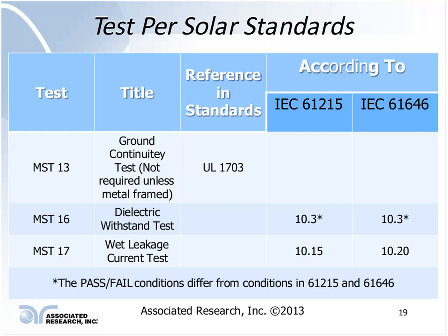There's actually a very similar table in 61730 that outlines the same information. I've basically broken that down and focused on the tests that I want to talk about here. And of course, this is in the interest of time. There are many more tests. Unfortunately, we can't get into them all right here, but hopefully we can give you a better understanding, if you are running these Hipot, IR, and leakage current tests, of how to do them and why you're doing them.